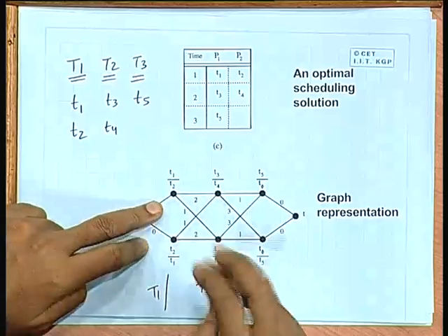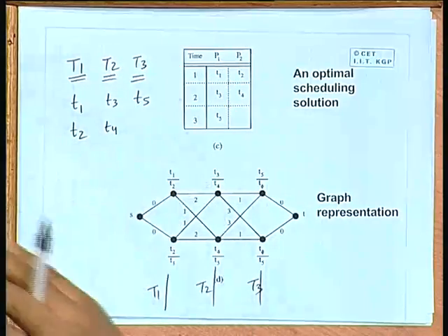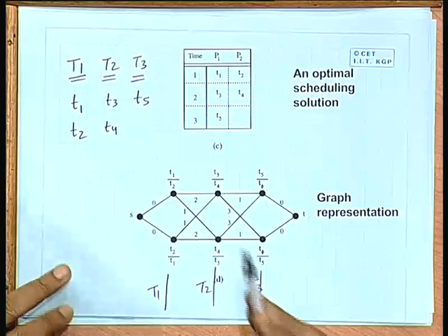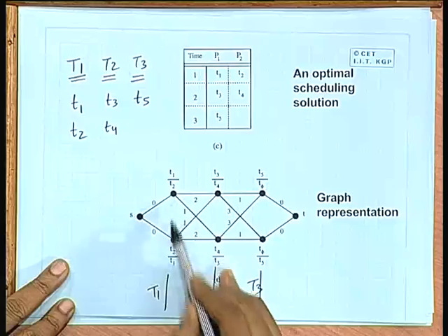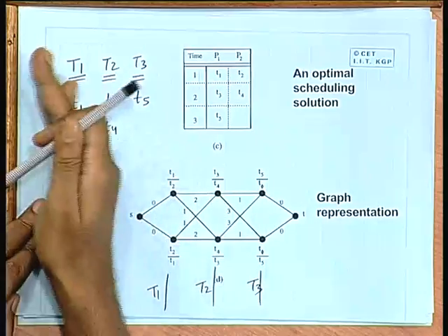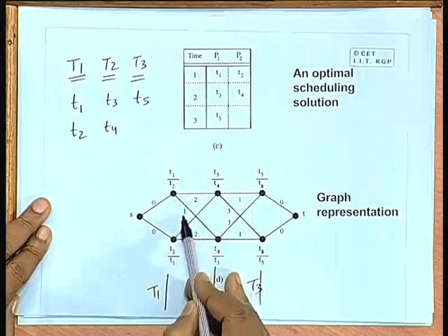So, this graph captures all the possibilities you can have in placing these two tracks across the two layers. Now, once you have identified the vertices, you also connect them with edges across successive tracks. These edges will have some weights.